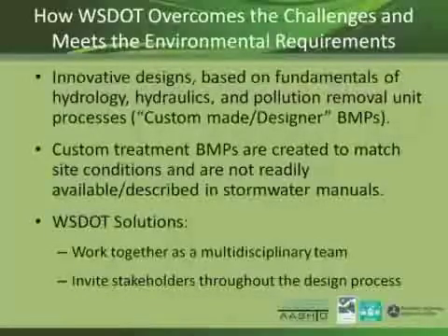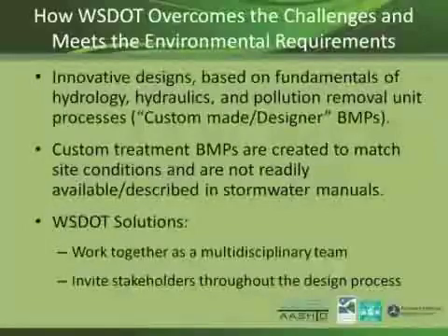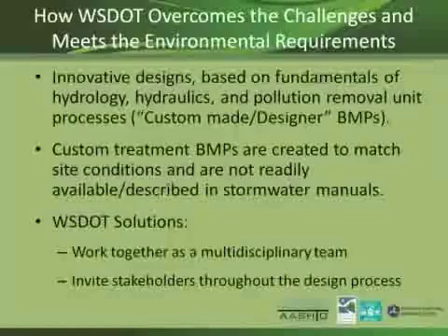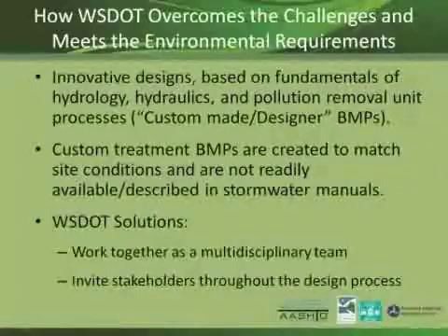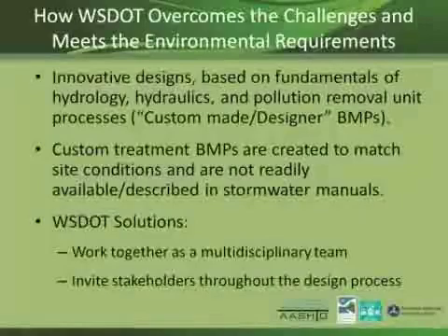So how is WSDOT going to overcome this challenge and meet the environmental requirements? As I mentioned before, we have only a few enhanced treatment BMPs available in our stormwater menu. Sometimes at certain locations those BMPs are not really applicable due to a physical constraint or some other issue, so we are forced to come up with a custom-made BMP. Just like Eric mentioned before, we develop a new BMP based on the fundamentals of hydrology, hydraulics, and pollution removal unit processes. This BMP is not in our menu, and I don't think it would be in any stormwater menu in the nation. When we develop this BMP, I think we need to work together with the other stakeholders and invite people to the design table so everybody can have an input and buy-in from the BMP. Next slide, please.